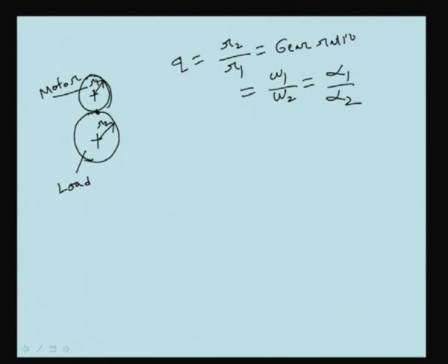Now, if I indicate the torque by the motor as TA, that is basically IA times alpha 1, where IA is the inertia of the armature plus this gear and alpha 1 is the angular acceleration, plus, if we make a free body diagram of this, you will see that it has IA alpha plus a resisting force F present here due to the other gear.